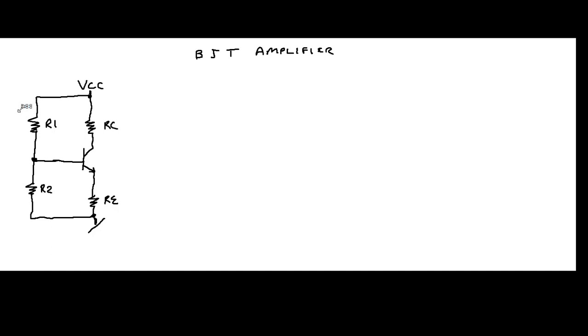When I'm talking about that, I'm talking about these two resistors in series, and you're tapping off the center right here. You have VCC up here, and you have a lower voltage, in this case ground down here. So depending on these resistor values is going to be your base voltage.